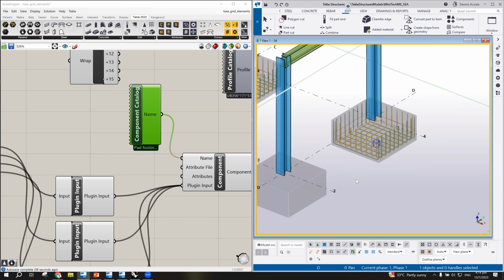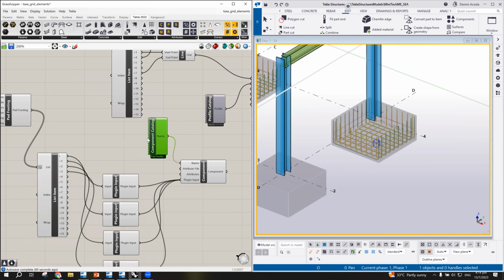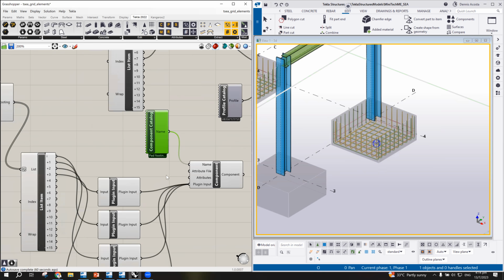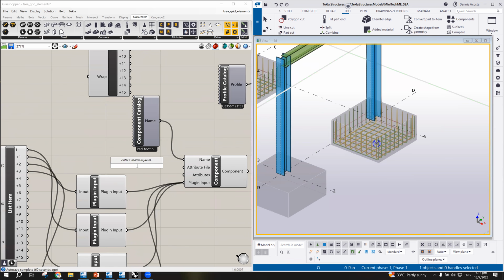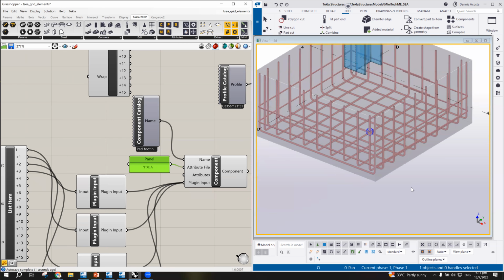So if you want to change the color of this, you need to type here attributes file. Just double click and then double slash panel. So you type here TC. Oh, sorry, I think capital letter TC. Okay, so that is the attribute file. If I link this one to the attribute file, yeah, see, it becomes red.